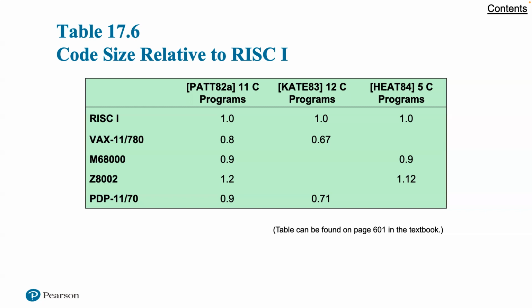On the IBM 390 system, instructions such as translate and execute and extended precision floating point divide reside in high-speed storage, while the sequences involved in setting up procedure calls or initiating an interrupt handler are in slower main memory. Thus, it is far from clear that a trend to increasingly complex instruction sets is appropriate. This has led a number of groups to pursue the opposite path.